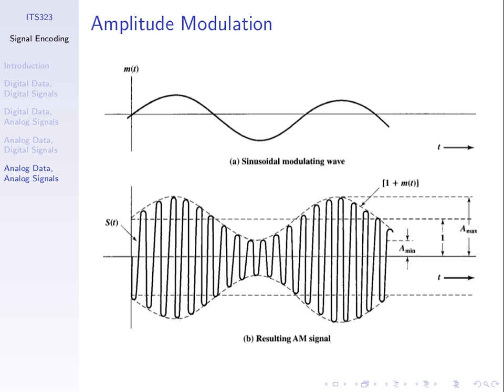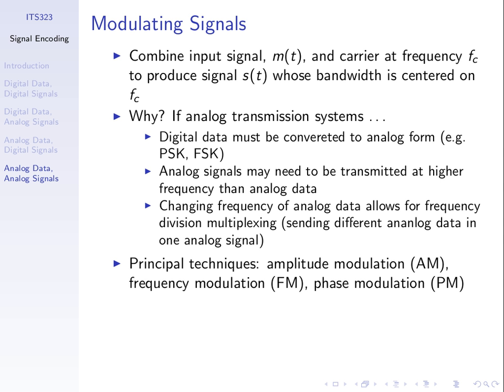So the transmitters can transmit at the same time, but they're both transmitting voice, which ranges from 0 to 4,000 hertz, or even music. If we transmitted at the original input signal, they would interfere with each other. But by shifting them to different frequencies, they do not interfere with each other. So the advantage is that we can transmit at different frequencies than what the original input is. Allows us to transmit things at the same time at different frequencies.